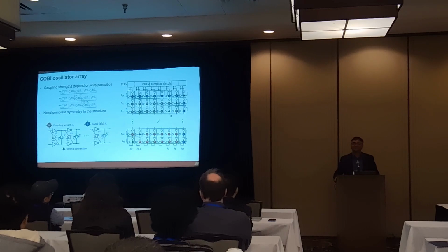I did some analog layout. The analog guys are nothing compared to these guys. These guys are extremely fussy. So I suggested, for example, that you could match resistances and capacitances even if you change layer, and they're like, no, we are not changing layers. We've got to keep it in the same layer to be perfectly matched.